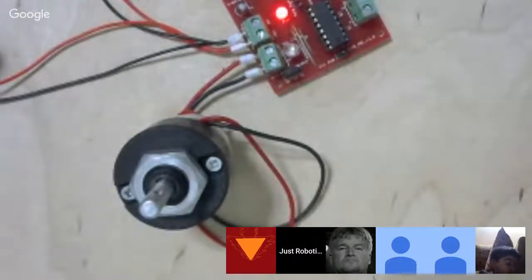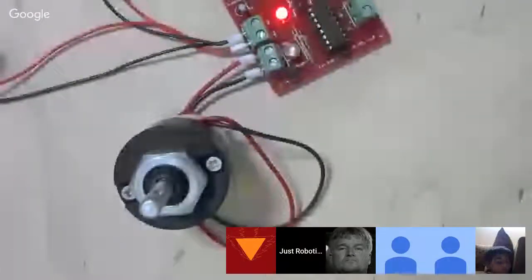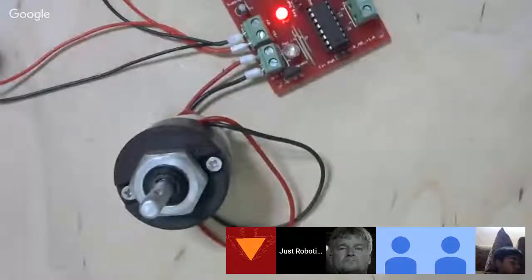So what we'll do right now, because we did digital write, and what you're talking about to generate a PWM signal is actually what is called analog write. Okay, digital write is just high and low. Analog write is anywhere between high and low, whatever values come in between. So when I say 0 to 5 volts, if I want to generate 2.5 volts, what will I do? I will have to turn on, turn off, turn on, turn off for an equal duration of time. Now it is actually analog write that we are doing, but let's look at how it's done.